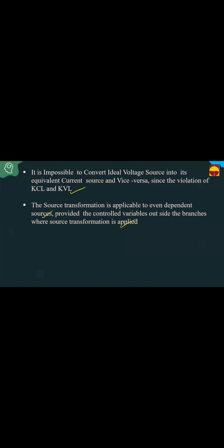So, for example, let this be a dependent source, plus minus, and let this be 10 I1. Let this be the resistance, 20 volts, and this is RL, the load. This is Rs. Now, what is the source? This is the control variable. This is a current controlled voltage source. This is a voltage source, but what is the variable here? Current is the control parameter.